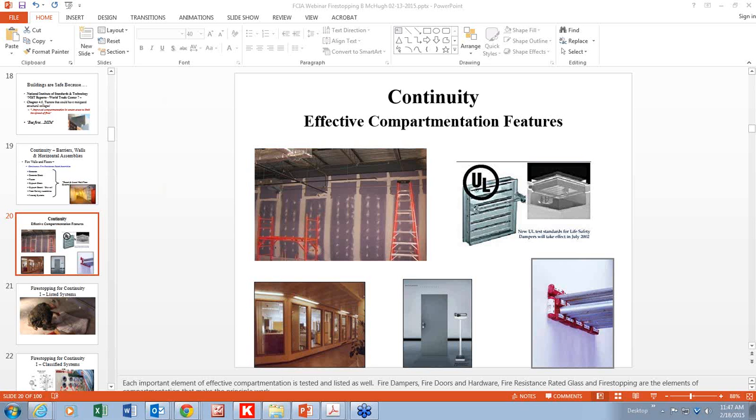Leakage, the smoke tight partition requirement, like the smoke and airtight specification speaks about. So in that case, we select the L-rated system, even though the partition is not fire rated? I mean, the barrier is not fire rated?